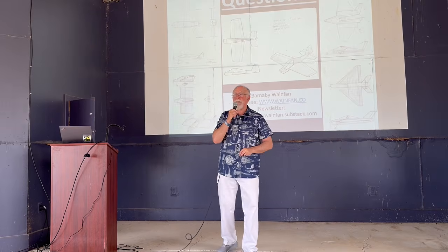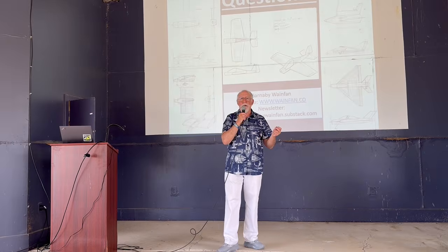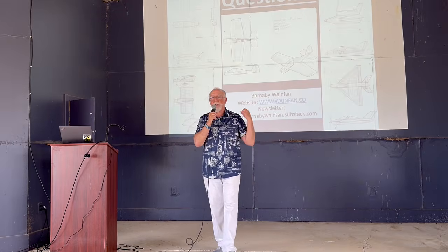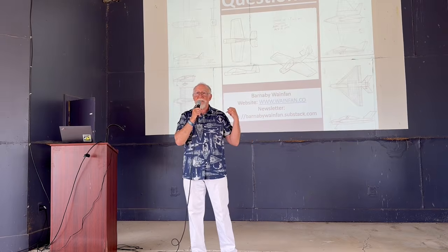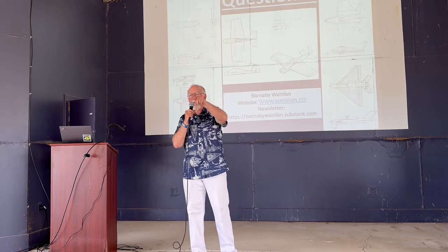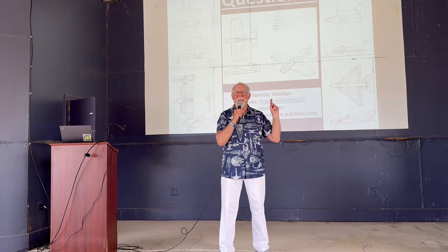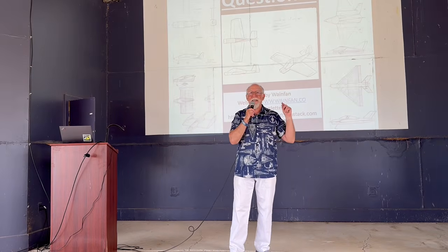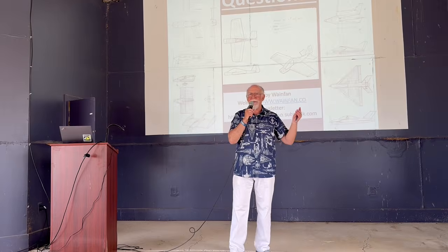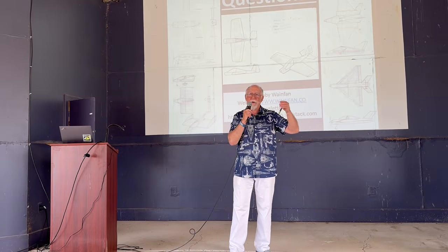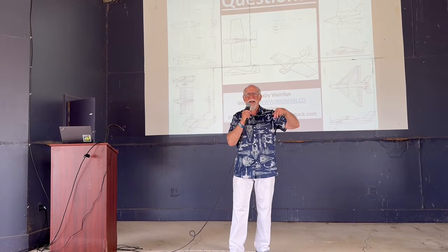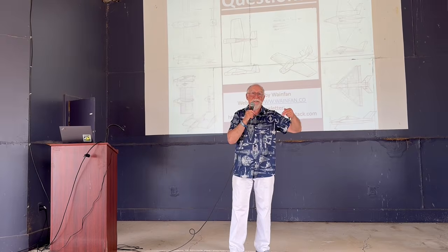Well, did it have a CG problem? One of the problems with canard airplanes in general is that if you're using the wings for the fuel tanks, you tend to get a big CG travel. That's why there are strakes on the EZs, and I think that's why Chet Nelson put strakes on the Sonic Cruiser also. But even though I knew the guy who actually did the design, it was all very proprietary, so I never got into the nitty-gritty enough to be able to tell.